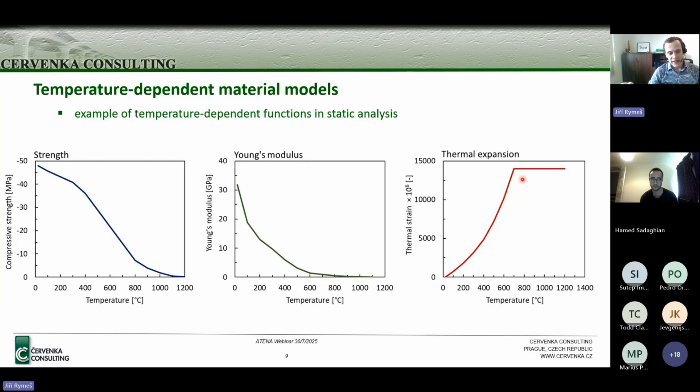And just after that, you for example switch to nonlinear material models and go to more complex loading history. In case of the fire analysis, this is not always true, because, for example, if you import the temperature data and decide not to take into account the reduction of the material properties and only account for the thermal expansion, you will get something which is probably